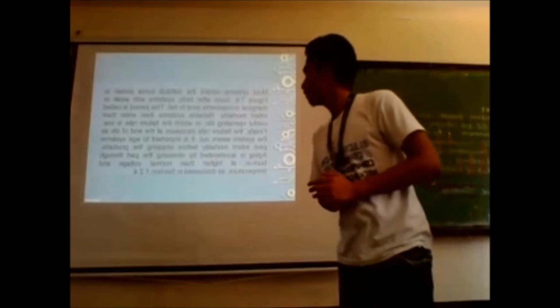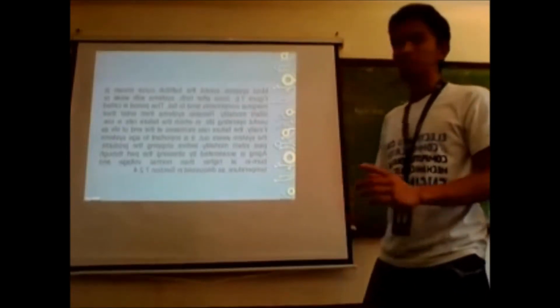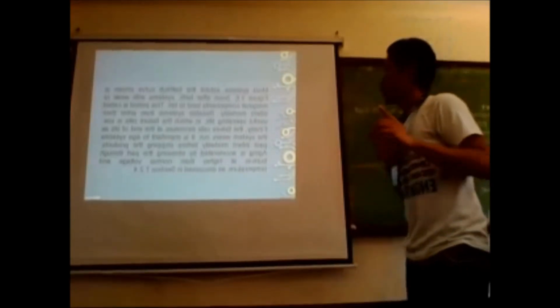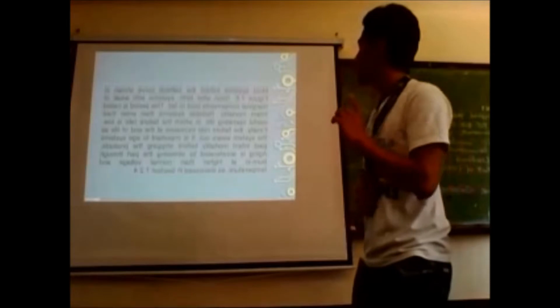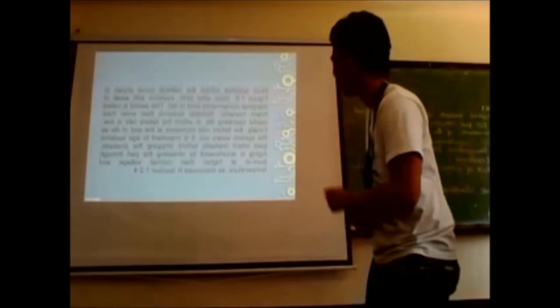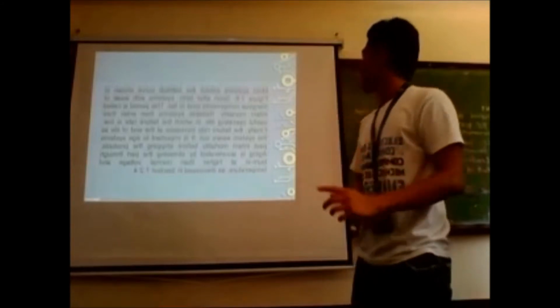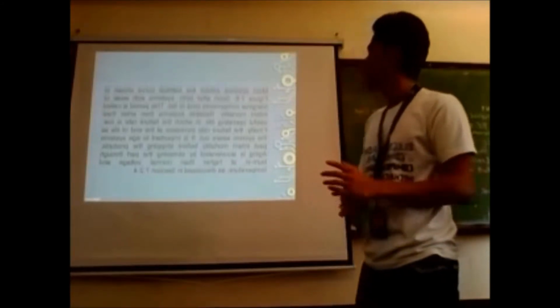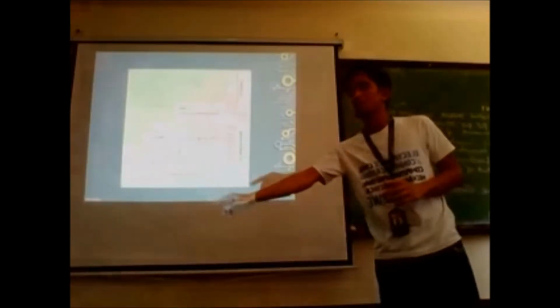Finally, the failure rate increases at the end of life. The system wears out. It is important to age systems past infant mortality before shipping products. Aging is accelerated by stressing the chip, or burn-in, at higher than normal voltage and temperature, as discussed in section 7.2.4.